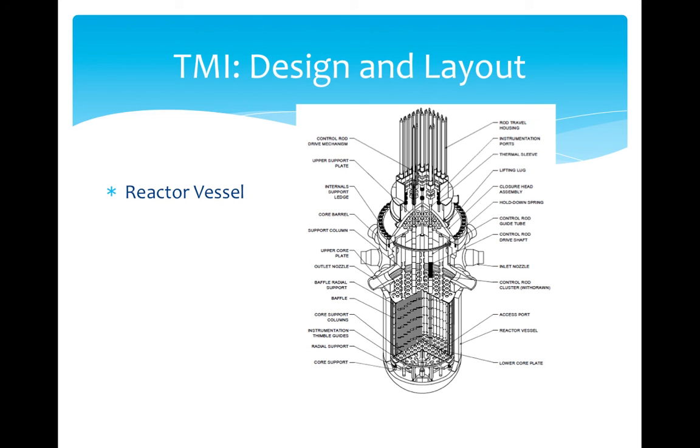On the primary side of the reactor, borated water was used based on the fact that boron is a neutron absorber and will aid in the ability of the operator to control reactivity during operation. The concentration of boron early in core life is around 2,000 parts per million and is reduced greatly as the core is operated for a longer period of time due to the fact that boron itself is very corrosive. Ion exchangers are used to remove it.